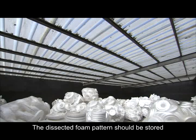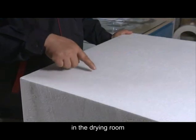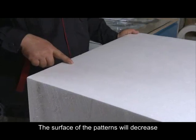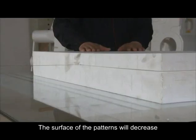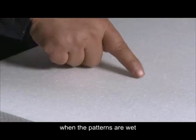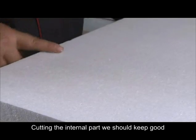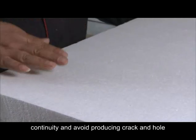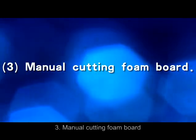The dissected foam pattern should be stored in the drying room if the patterns are affected with damp. The surface strength of the patterns will decrease and the pattern is easy to deform when the patterns are wet. Cutting the internal part, we should keep good continuity and avoid producing cracks and holes. 3. Manual cutting foam board.